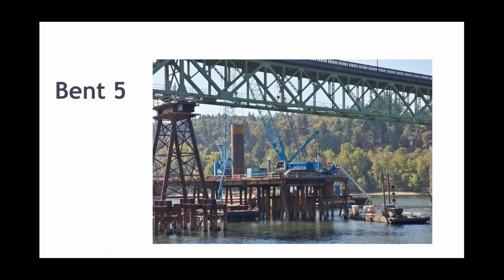Another shot at Bent 5, and I like this photo because it shows, one, the existing structure that's on temporary piling, and how close we are to that structure. And two, this whole setup, oscillator and crane, are working on a temporary trestle. As this oscillator is working to get this casing down and back out of the ground, tremendous lateral forces are being applied through that yoke to the crane, and then the crane is transferring that force to the trestle.